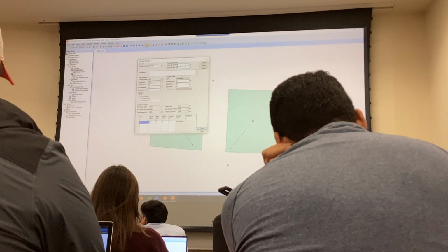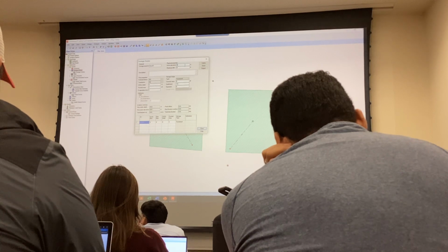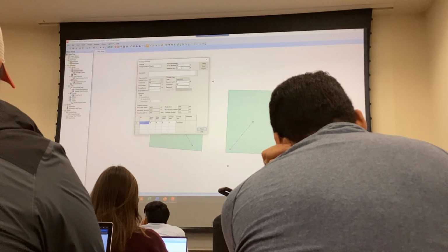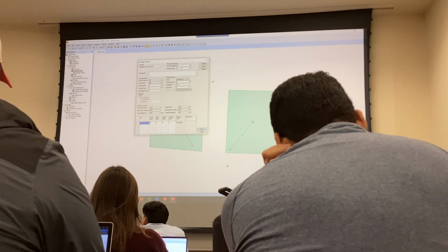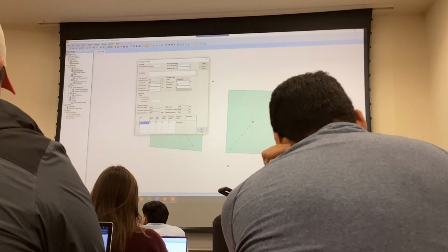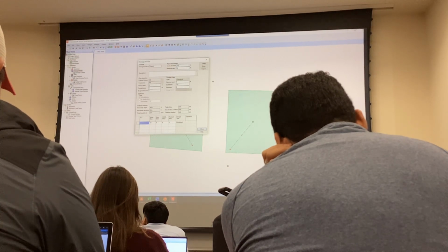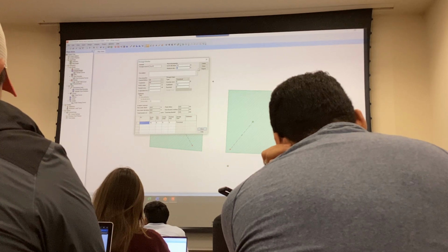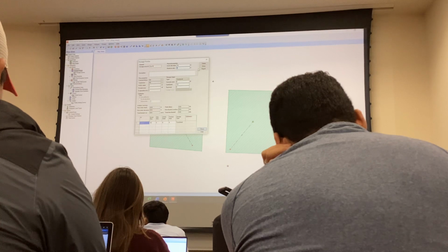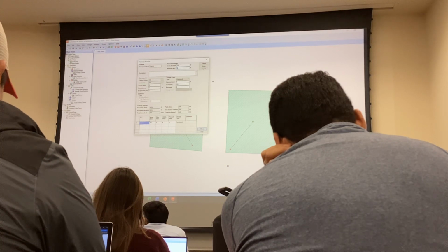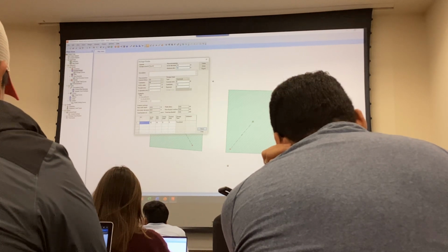Now, it's not clear right now why you need that, but when we go on to the next thing, you will realize that that's quite important. Okay? So let's say the invert of my detention basin is 10. Okay? And then my maximum elevation, let's say, 16. So my depth, therefore, is 6.